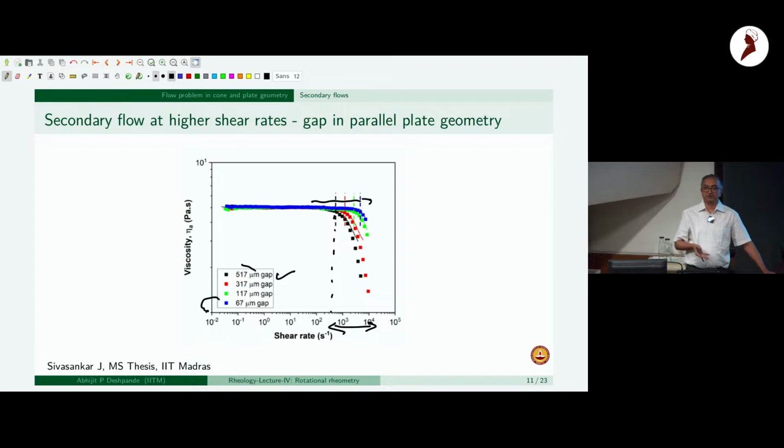One is of course to do flow visualization and see whether, at the edges, and also it's clear that the velocities are larger towards the edges because of omega r. So you would tend to look for secondary flows near the edges. If you do flow visualization there and you don't see secondary flows, you can safely assume that they are most often not there in the interior. But if not, you will have to do some analysis of this kind and then look at scaling and say that, okay, it corresponds to our understanding.